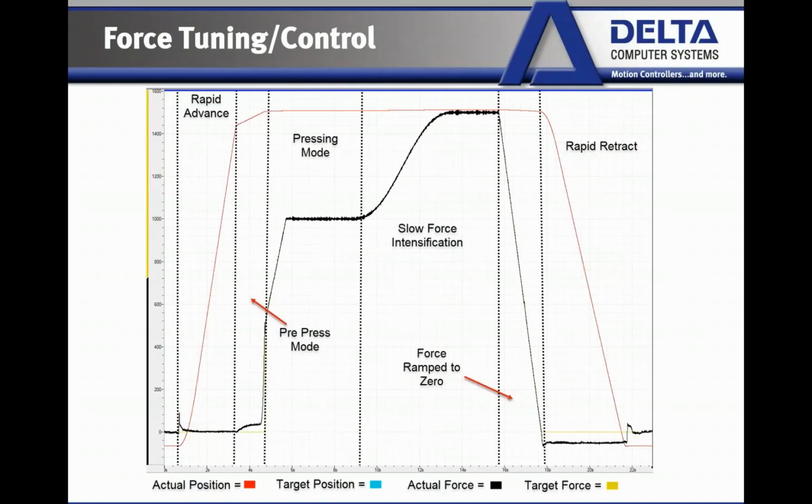What's going to end up happening is the cylinder is just going to slam into the part below it because it's going to keep building up because it's not seeing any feedback. So this is why we really want to wait to go into force control until we've actually made contact with the part, because then we're getting real, good feedback, and we're not going to damage anything.